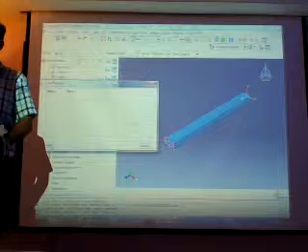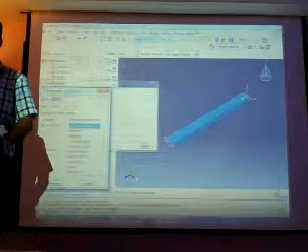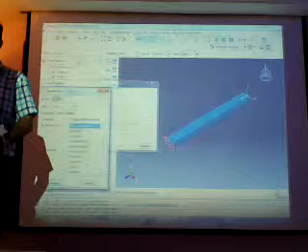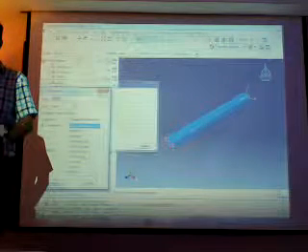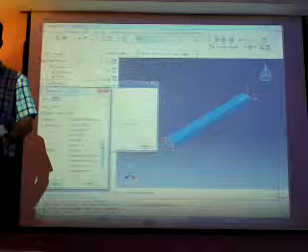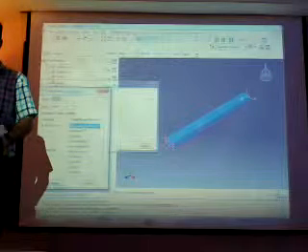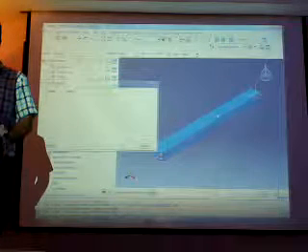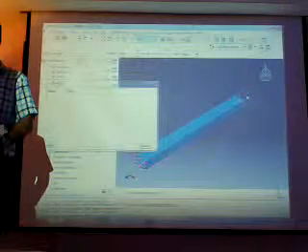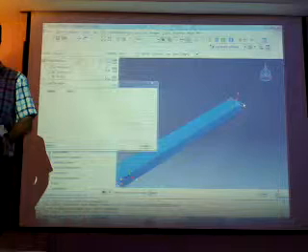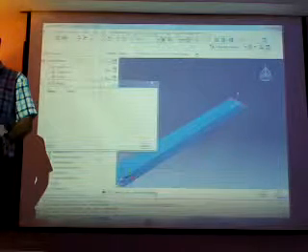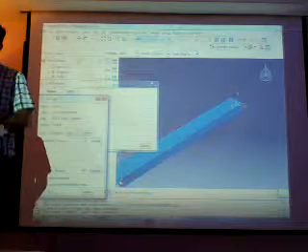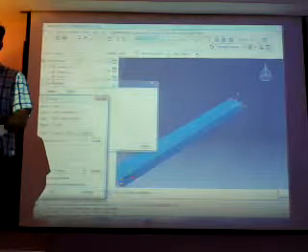We are going to create our load, create, and you can see different kind of the loads. For example, pressure, moment, and any kind of load depend on your simulation. We take first one, for example, concentrated force, continue, and now we need to define a region. I take this point, done. This is the force in X direction, this is in Y direction, and this is in Z direction.